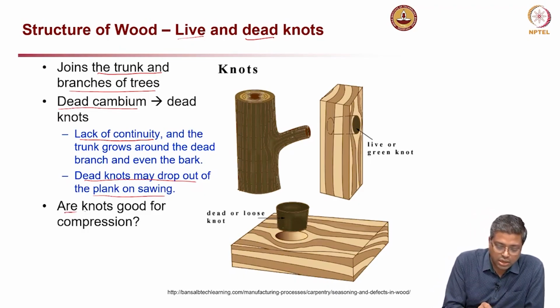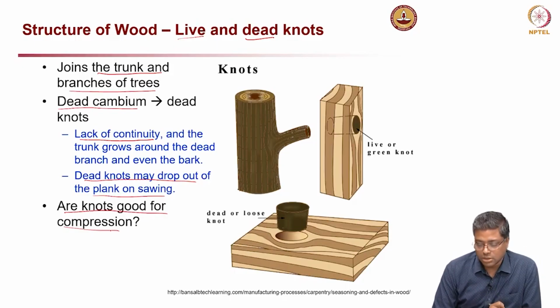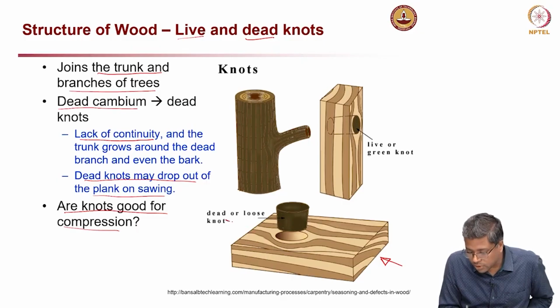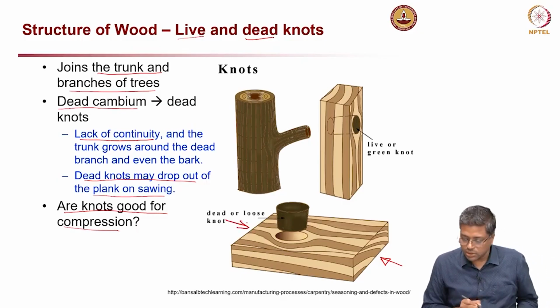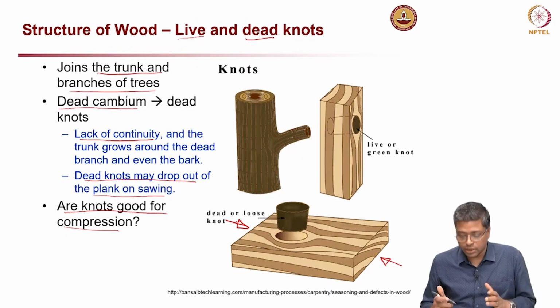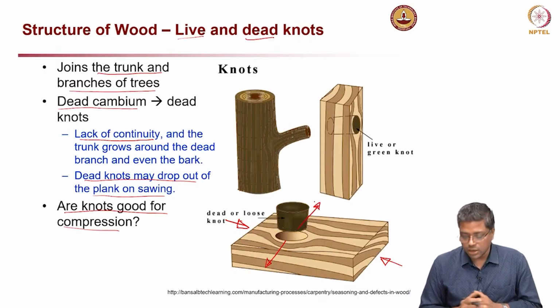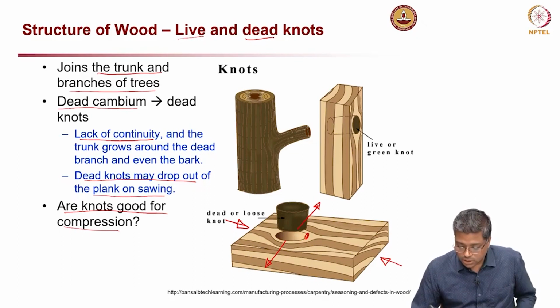Okay. So, the question here is, are knots good for compression? Now, look at this picture here. If I compress the wood in the direction parallel to the grains, what will happen is a lateral stress will be generated here, and the stress concentration will happen here.